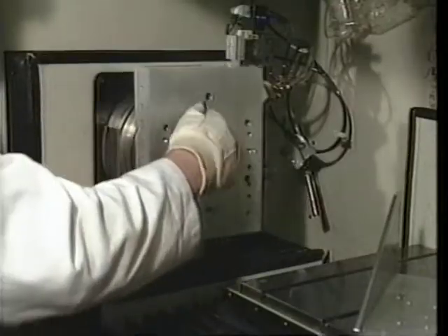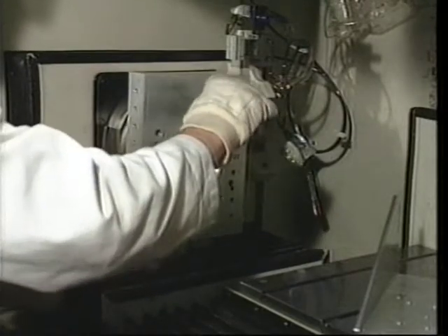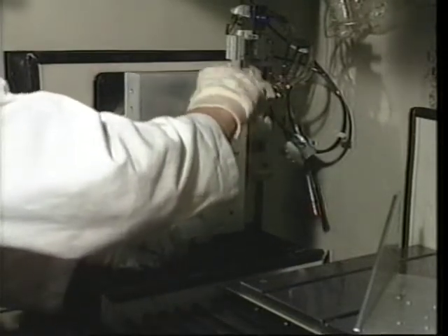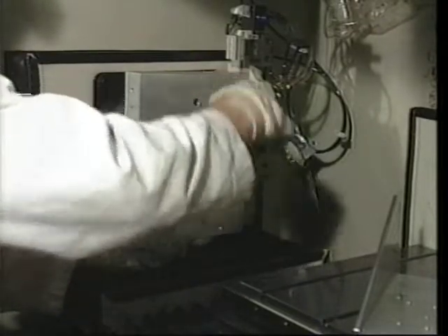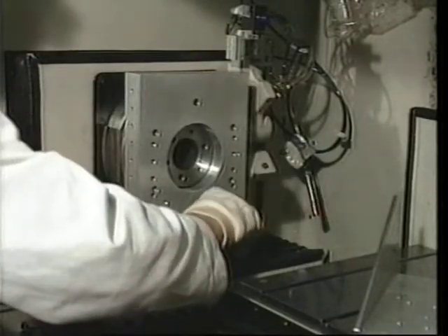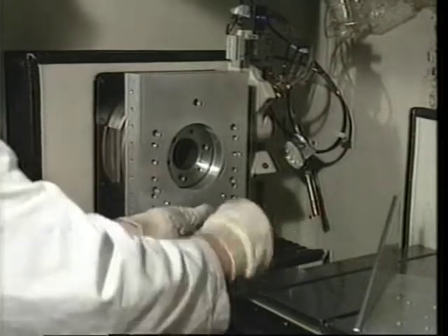In neither step will the straightness error of the straight edge be removed from the measured data. However, if the magnitude of the straight edge error is significant, the validity of the squareness measurement can be jeopardized. In today's lab, we will ignore the errors in the straight edge. In setting up for this measurement, a precision index is mounted to one slide, in this case the z-axis slide. Here the spindle chuck has been removed and the index platform is being attached to the spindle housing on the z-axis slide.